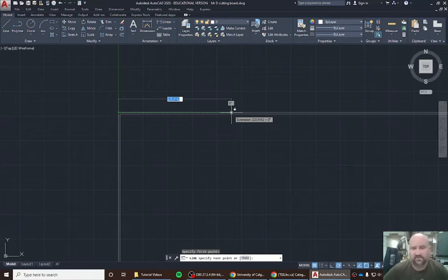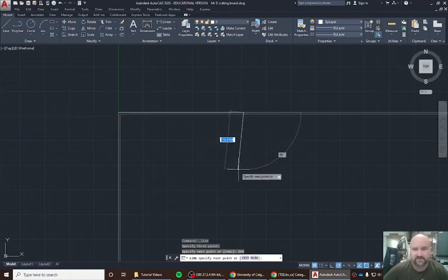So our cutting board should be 254 millimeters long. I'm just going to type in 254. You'll see that blue box turns white. 254, hit enter. I can now continue my line, so I'm going to move my cursor down until I get another green line. Our cutting board should be 200 wide, so I enter that.